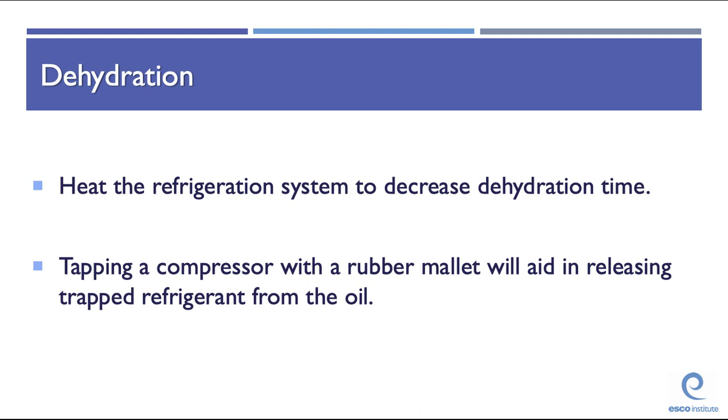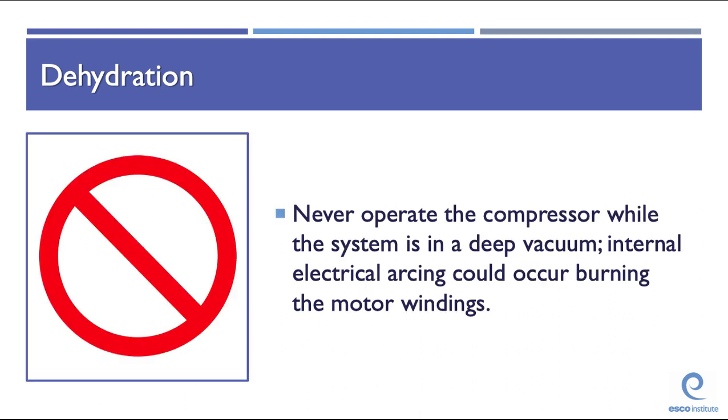You can heat the refrigeration system to decrease dehydration time. Tapping a compressor with a rubber mallet will also aid in releasing trapped refrigerant from the oil. Word of warning, and very important, never operate the compressor while the system is in a deep vacuum. You can actually create internal electrical arcing, and it can burn out the motor windings.